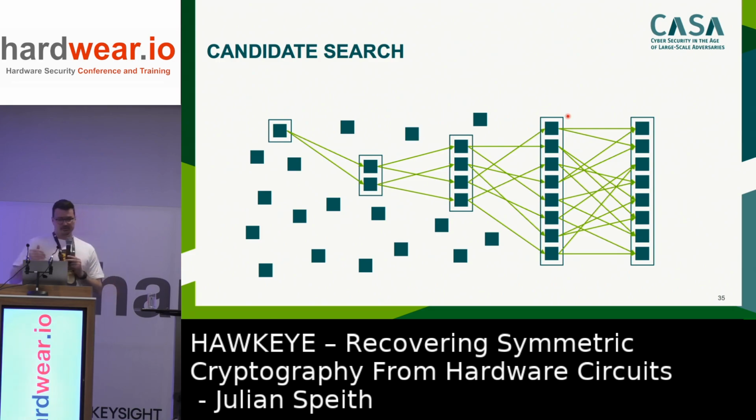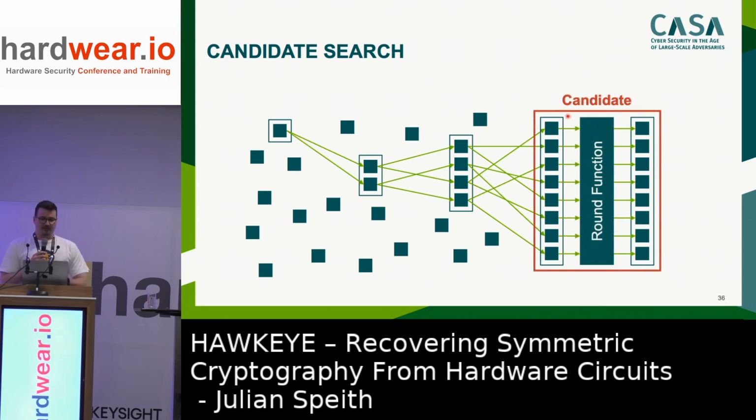And this is because of the properties that we've just talked about. So you only go from state register to state register, and from state register maybe to ciphertext register, but you don't go anywhere else. So you are stuck with your registers, and you can differentiate between state and ciphertext. So if I stop propagation at every ciphertext register or every ciphertext flip-flop, and only assume that in this final set of flip-flops that I've discovered there are only state flip-flops, then this will saturate because my register in this case only has 8 bits. In the AES case, it only has 128. So at some point, these sizes won't grow anymore. And if we find that they are the same over a couple of iterations,